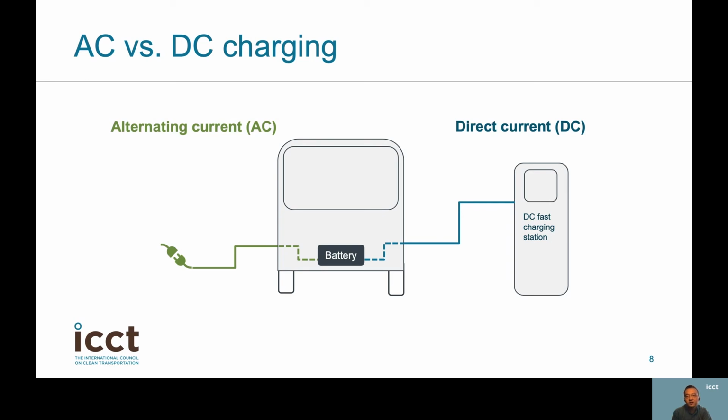For DC charging, the electronics required to convert power from AC to DC are placed outside the vehicle, and the DC charger provides DC power to the BEV. These chargers are currently capable of supplying power up to approximately 350 kilowatts, and future product forecasts indicate that power supply could be as high as 3 megawatts.